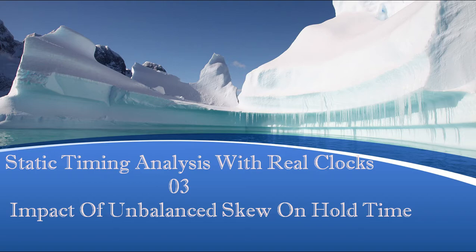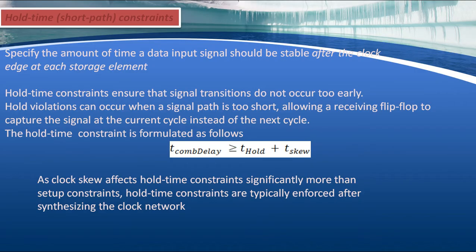So this is how we handle unbalanced skew for setup time. Right now we go for the impact of unbalanced skew on hold timing and how we cure this. Let me go through it. Hold time, that is known as the short path constraint, specifies the amount of time the data input signal should be stable after the clock edge at each storage element.